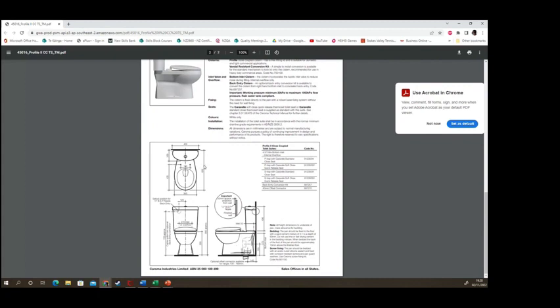Pretty heavy moving a close coupled toilet in, especially when you've got to lift it over the brackets, when they've got those internal brackets like the L bracket. So they can be quite tricky, and if they've got the little gooseneck type bit as well, you've got to try and line up all that. If it's fully flush back to the wall, then you can't really see if it's leaking very well. You can only poke your head through the little holes, either where the seat goes. Sometimes they have a hole on the side as an alternative inlet, so you can sometimes see in there, but occasionally you can't really see the whole picture.